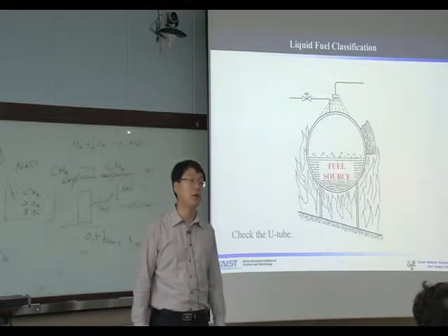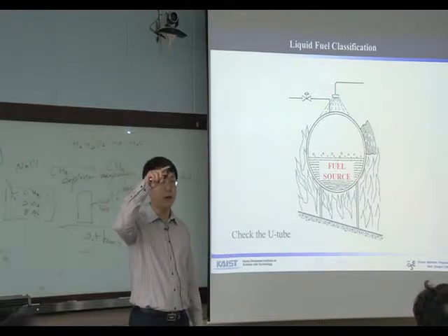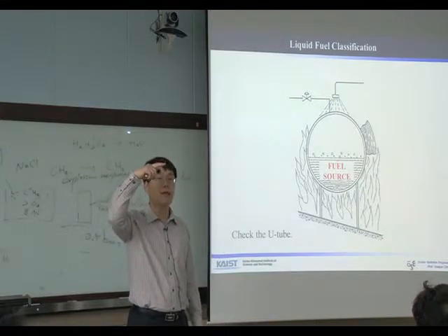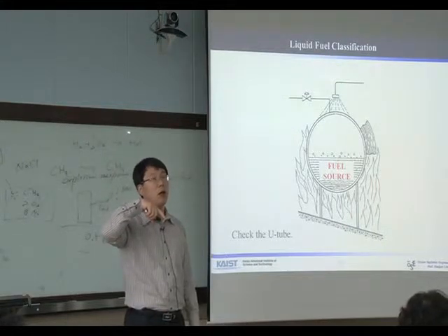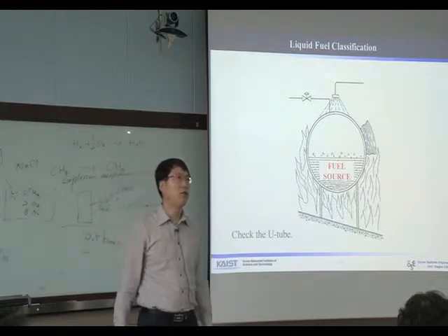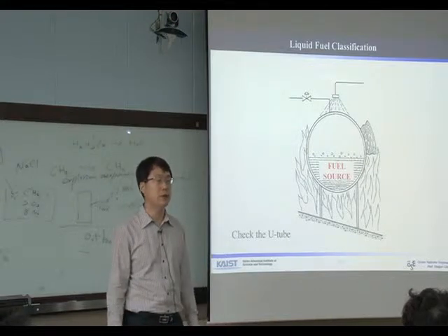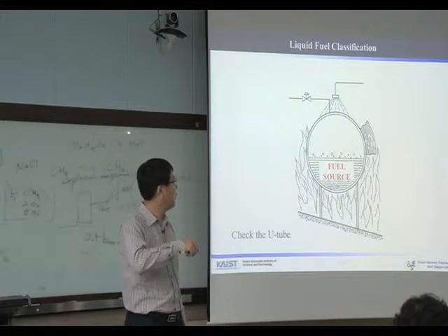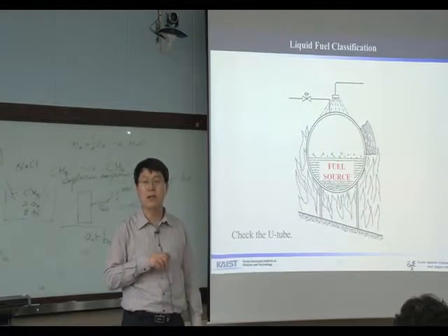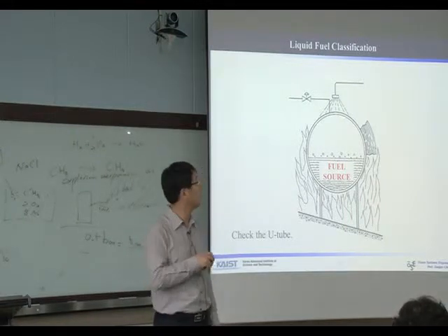But if the temperature of the material is increased by the fire, the yield strength of the material decreases very rapidly. So at around 450, we usually assume that material strength is decreased 30%. So it is very important to cool down the material of the tank. So this is the second objective of the deluge system.